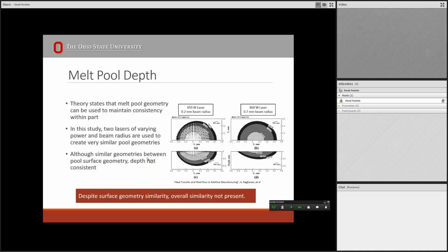One thing I've noticed too, in the depth view, you can see some of the swirling happening that we've talked about recently, what's the name? Starts with a G. Marangoni. Yeah, Marangoni, thank you. Marangoni effects in that pool, but with the concentrated laser, you definitely see a rise in the fluid flow vectors.